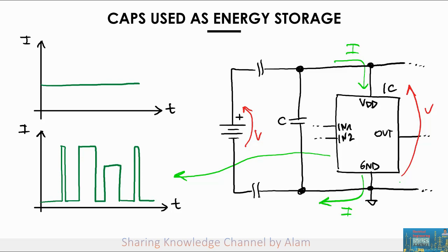So if we look at this current and assume it is the current requested by an integrated circuit, if you didn't have a capacitor, you would start from the nominal, let's say 3.3 volts. Then when you get here, you will get a quite significant drop.